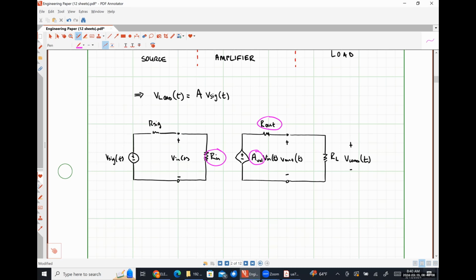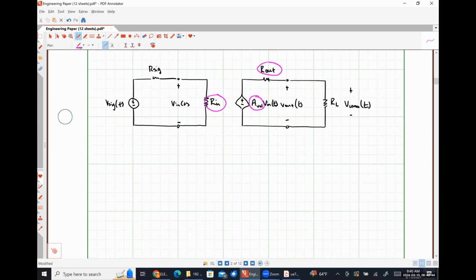So in this particular network, we have a single input signal, Vn. But what do we know about op-amps? They have inverting inputs and non-inverting inputs, and we could potentially apply two different input signals to those terminals. So we need to account for the fact that we might have two inputs, whereas this model only gives us access to one, okay? So I'm now going to introduce the practical op-amp model, and it's going to be incredibly similar.